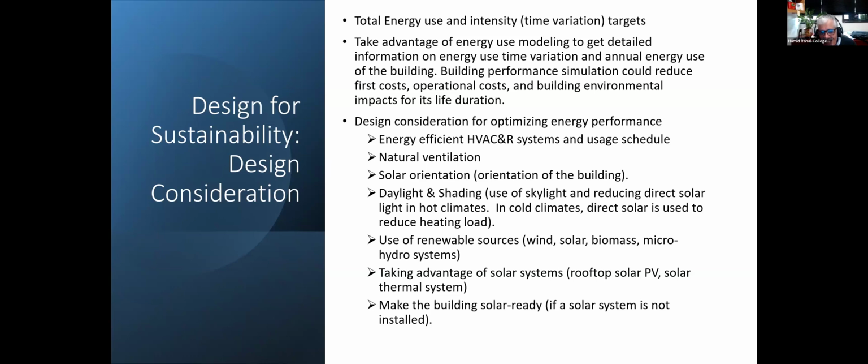So you need to look at, for example, in Long Beach, the best is if it's faced south and solar panels are at an angle of 15 plus latitude. So we are at about 35-degree latitude, plus 15 is 50 degrees. If you orient your solar panel facing south at a 50-degree angle with respect to horizontal, then you get the maximum radiation and the best efficiency out of it, and the maximum electricity can be generated. So the orientation of the building becomes important in this case.